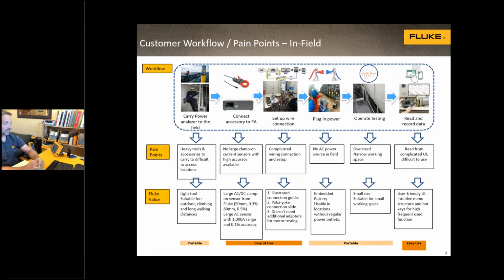And of course, the portability. Wiring with the bench analyzers can be quite complicated. We've made it pretty simplified, just like we do with our power quality devices, where you can simply plug in your voltage probes, and you have a shunt already built into the top. You don't need external shunts. A lot of bench units require external shunts to be used.